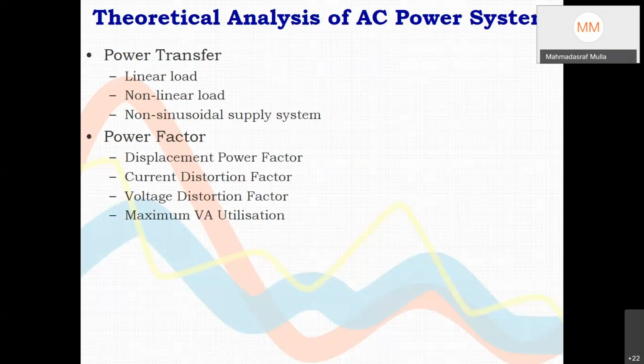Then this term is very widely explored, power factor. Immediately a student will say cos of the angle between voltage and current. But now the scene is different. You are drawing non-sine current. So how to define the angle between voltage and current? Your voltage itself is having a non-sinusoidal component. So how to write power factor?